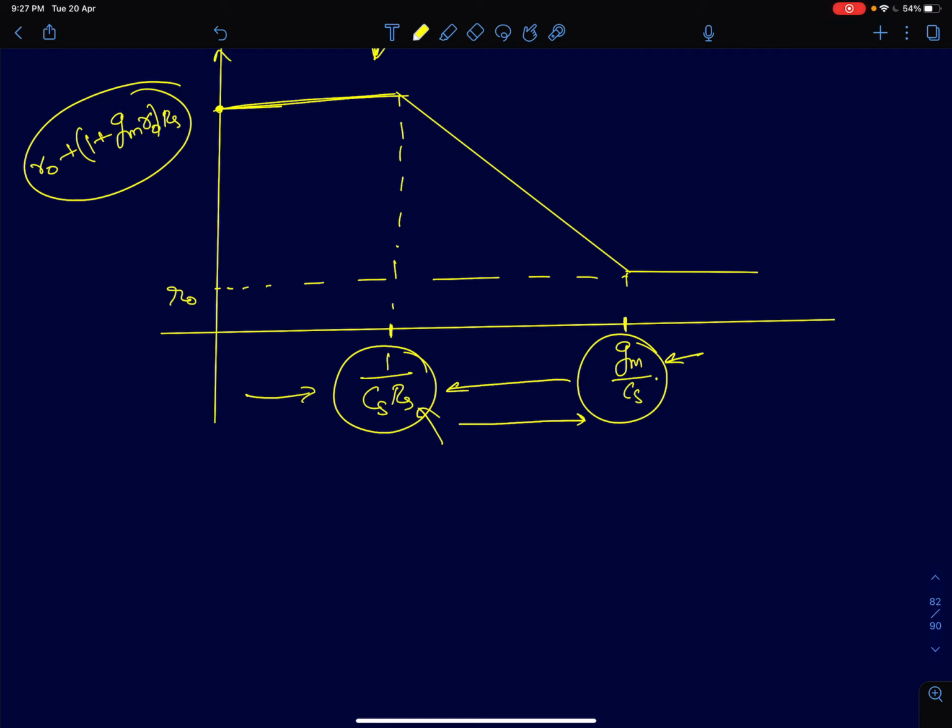The second thing, we saw how the input impedance changes as a function of frequency, and we also saw how the output impedance changes as a function of frequency. And we mentioned the usual points that common gate amplifier is typically more preferred to be used as a current amplifier or a current buffer. As a voltage amplifier, it will still find applications provided you're driving it with a very low source resistance.